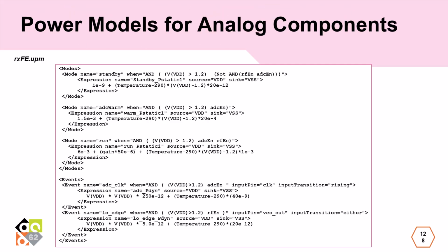One of the primary things we wanted to capture is the long warm-up time for the analog-to-digital converter reference voltages. So for our power model, we have 3 states, including standby, where the power is on but everything else is disabled; that ADC warm-up time, which is before we've turned on the high-power RF front end; and a full run state where everything's on.